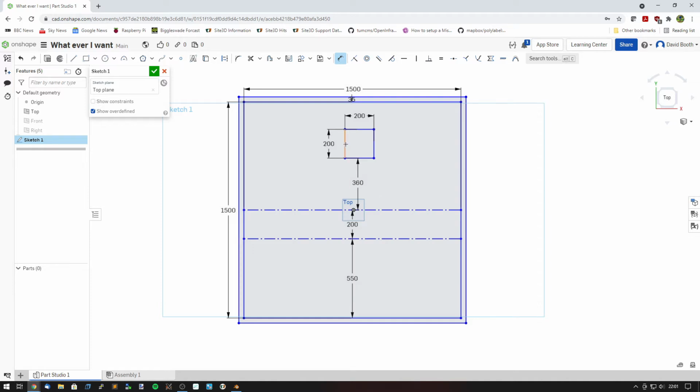And the same, I can click this one once and you can see I can set that dimension, or I can select another line and it'll choose that. So I can then select this one and say, well, this one should be 650 mil offset, and it'll move it as it needs to be. So you can constrain things as they need to be, and just drag that one over that side so we can see exactly what's going on. Move these across to somewhat similar to what the actual example was showing us.